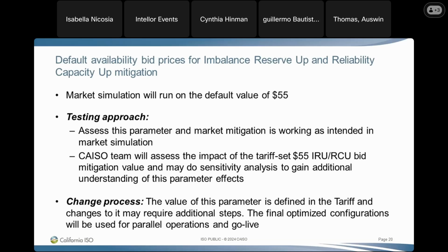So essentially, if you provide any upward imbalance reserves, that will be treated as energy in terms of enforcing the energy limit on a hydro resource. Currently, for example, you might have 100 megawatt hours fully awarded day ahead as energy. If you have any imbalance reserves awarded day ahead, they will reduce your day ahead take. Has there been any thought about whether it's appropriate to have the imbalance reserves fully contribute to the energy limit for hydro resources?